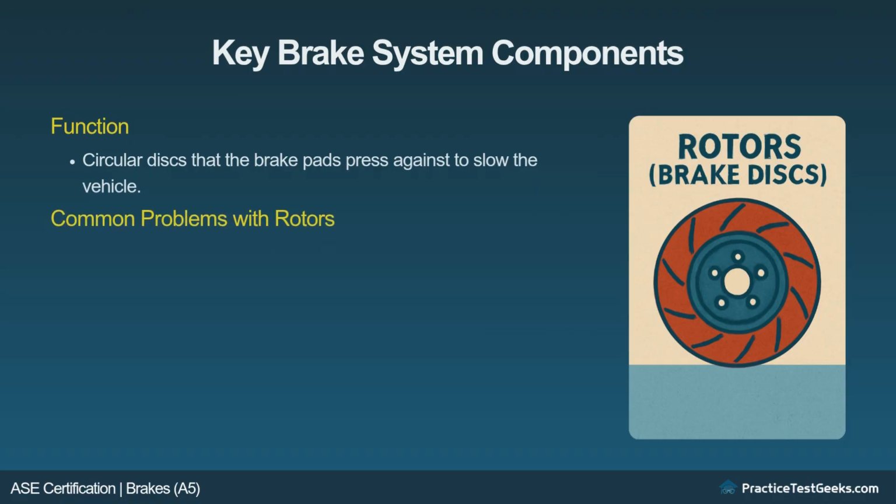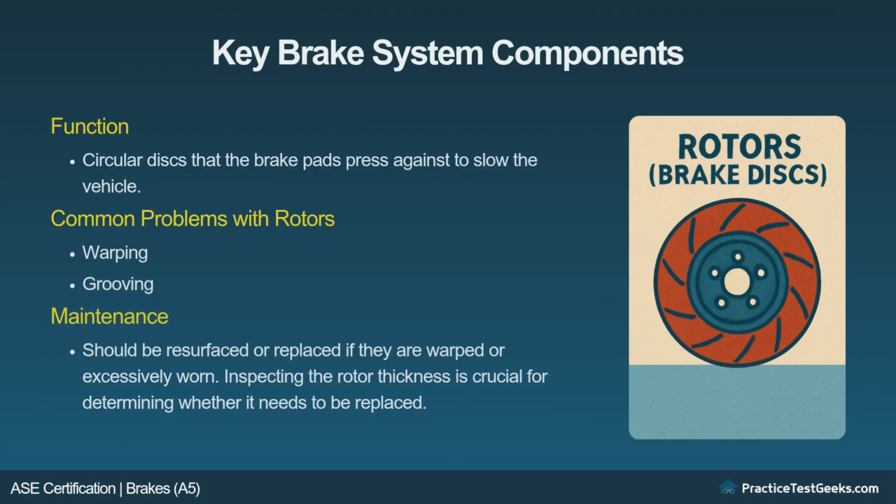Common problems with rotors. Warping. Heat buildup can cause the rotors to warp, leading to vibration when braking. Grooving. Over time, grooves can form on the surface of the rotors due to contact with the brake pads, affecting braking performance. Maintenance. Rotors should be resurfaced or replaced if they are warped or excessively worn. Inspecting the rotor thickness is crucial for determining whether it needs to be replaced.